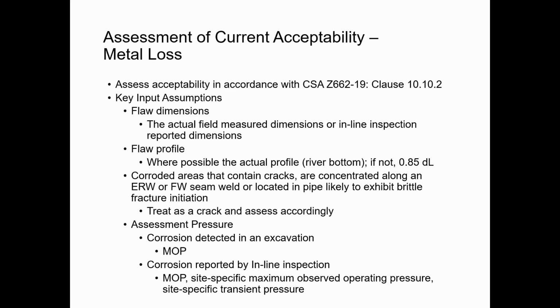It's not that big a deal when making decisions in the field for repair, because it doesn't hurt to be a little conservative in making your repair decisions in the field. But when it comes to analyzing inline inspection data, I realize that it costs more for the vendors to provide the operators with predictive failure pressures based on the effective area approach. But ultimately, it might save you some digs, so you can balance the cost of the additional analysis versus the potential cost savings from reducing the number of excavations that you have to do.